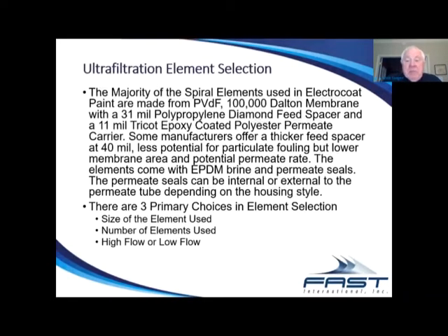So if you translate that to microns, it's about a 0.02 micron pore size. That material has a feed spacer of a 31 polypropylene diamond style and a permeate carrier that is 11 mil tricot epoxy-coated polyester. Pretty much all of the manufacturers that I'm aware of manufacture the elements with those components.